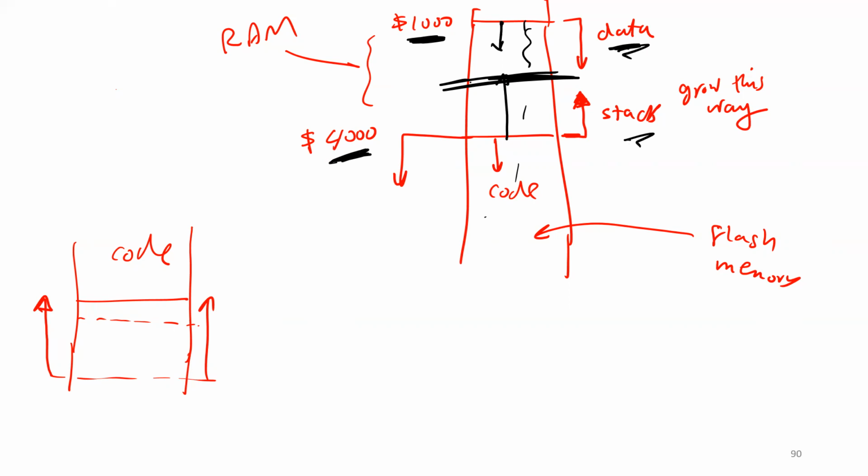All you have to do, guys, in the very, very beginning of your program, is initialize the stack pointer. And that's it. You can initialize the stack pointer to 4,000. Is that okay? Then you read, write, and the stack pointer is automatically updated when you pull or push. You just initialize it in the very beginning.